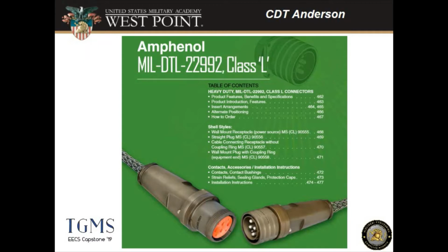We agreed that there may have to be two versions of the tactical generator monitoring system, one that can serve higher power loads and one that will serve lower power ones. We decided that we would be in the market for lower power loads and would thus cap the load size to a 50 amp current capacity, serving as a constraint on our design. This constraint helped us to fine-tune what kind of parts we were going to need to order for the system.